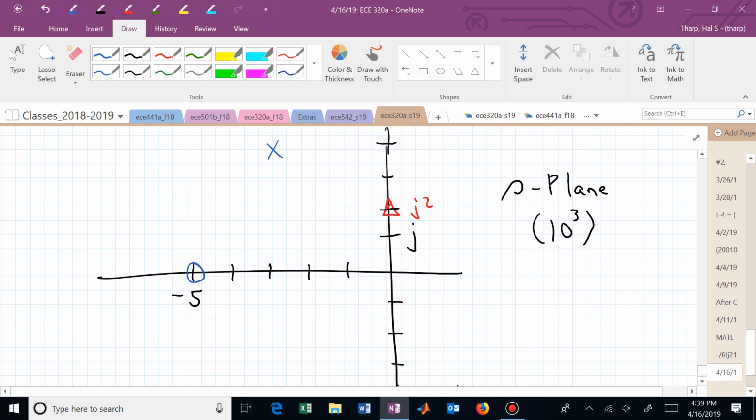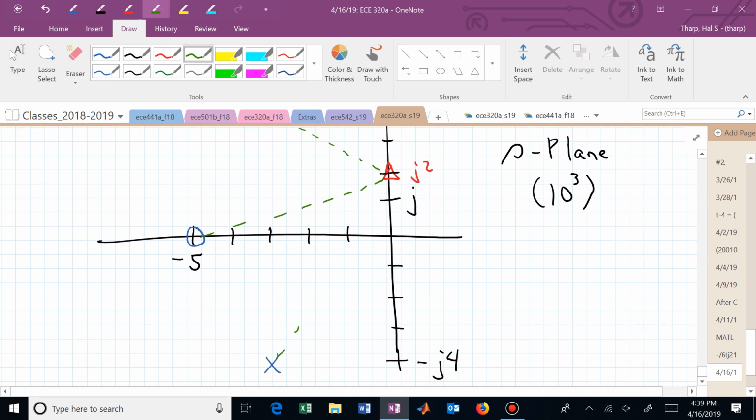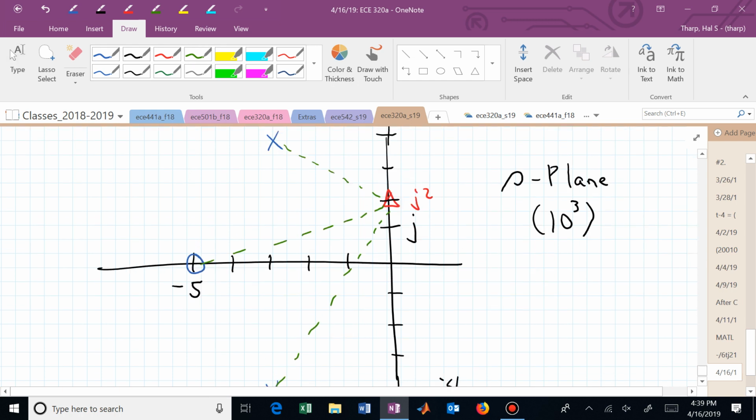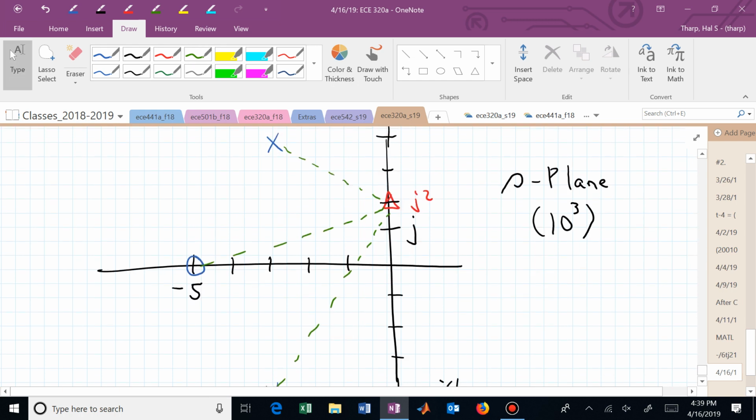And what am I going to do? I'm going to find all of the contributions of these poles and zeros. I need to find the distances that each of these are from that triangle and their direction. This now has a negative angle. I could say this is theta p1, and this is the length from that first pole down to that location. I have this direction of my zero with a length of L sub z, and you can find that by the Pythagorean theorem. It's 5 squared plus 2 squared, square rooted. Again, we've scaled this all by a factor of 1,000.